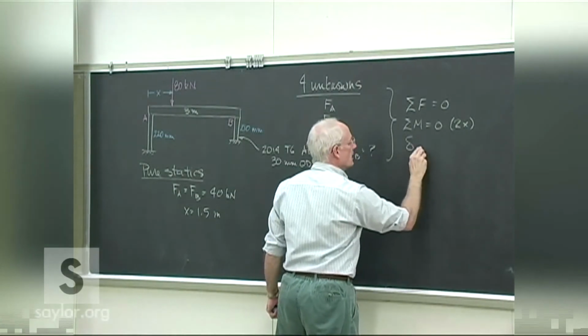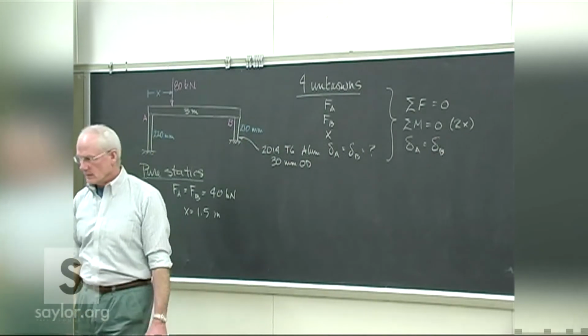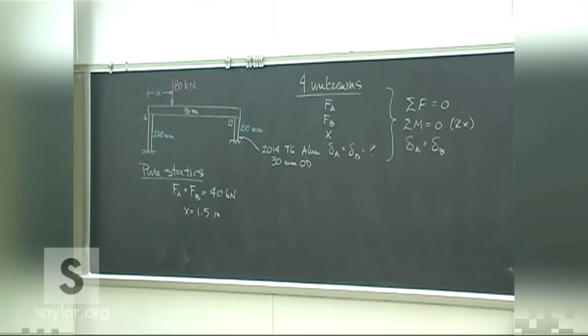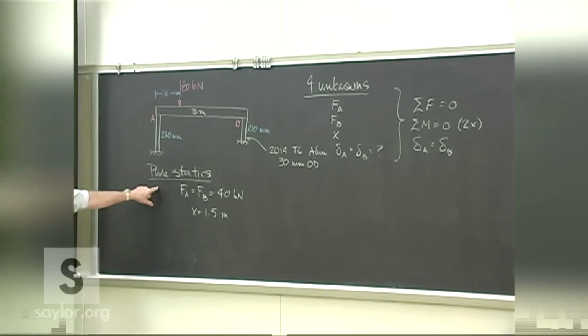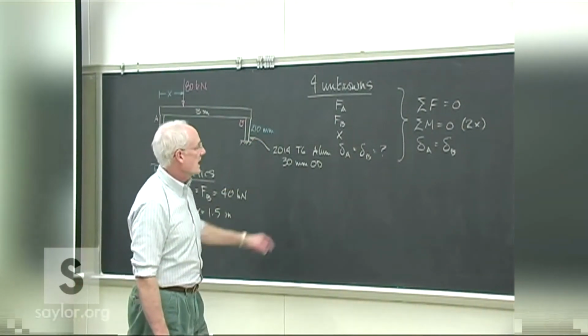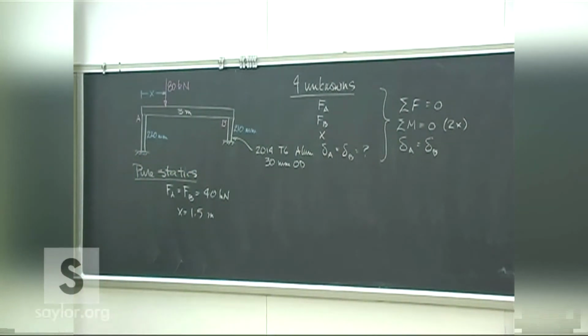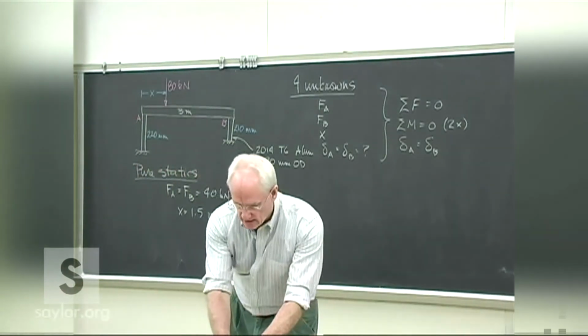And that's something we never had in statics. But now that we're looking at deformable solids, we do have that kind of thing as a way for us to solve these problems. In statics, this would have been an indeterminate problem. More unknowns than we had equations. Remember, we only have 3 equations in statics. Now that we have the deformations, we have other ways we can make these calculations as needed.